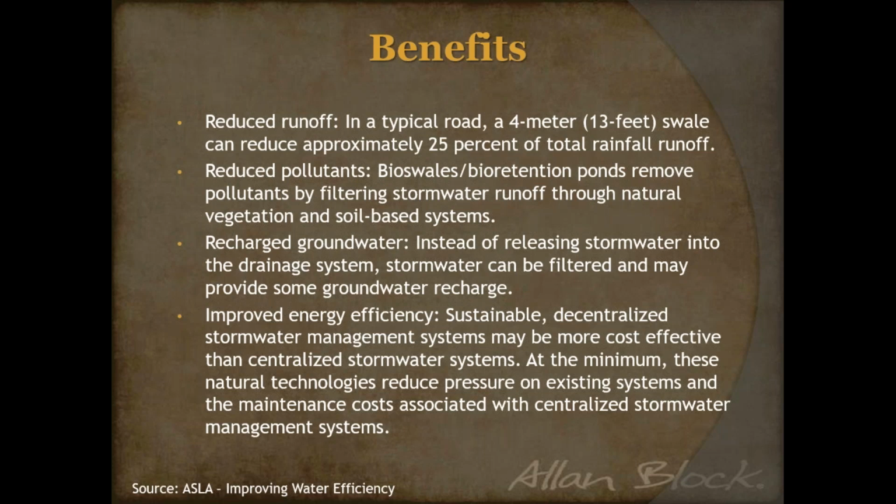And we know, and this is from the American Landscape Association, that if you had a 13-foot or 4-meter wide bioretention swale or bioretention pond, that's going to reduce the total runoff by almost 75%. So you're only going to get 25% of that total runoff. And that's quite a bit.